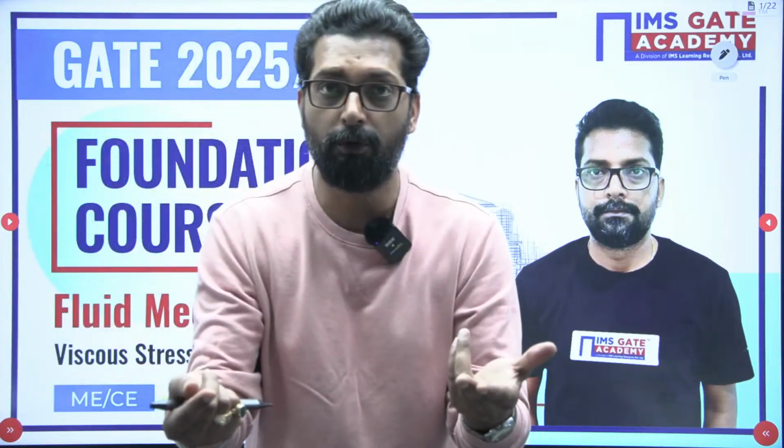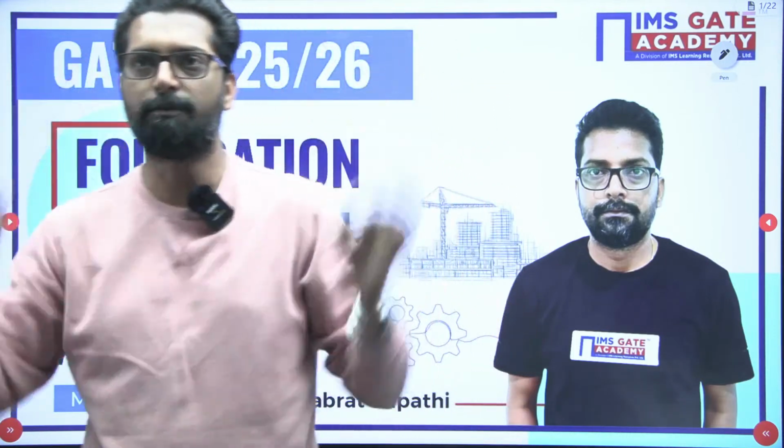My dear, sometimes students get confused and ask, sir, during Couette flow, is the pressure constant or not? It is up to you; you may take the pressure constant or not. Fluid will ultimately flow due to the boundary displacement only, so we can neglect the pressure. For the simple analysis of Couette flow, first we assume the fluid flows without a pressure difference, that means the pressure is constant in the flowing direction and is not varying. So how does the fluid flow? The fluid flows due to the displacement of a boundary.